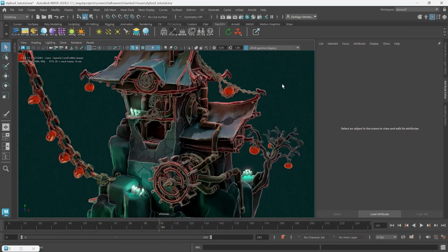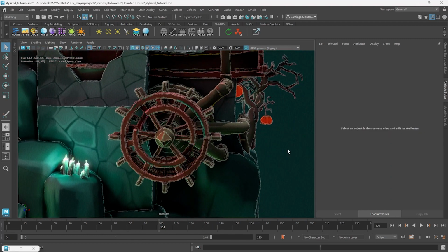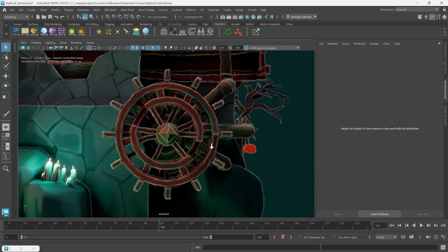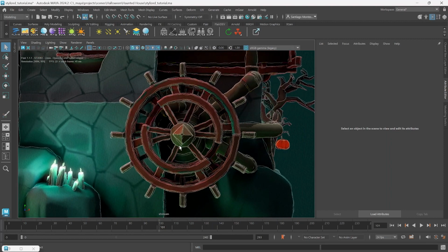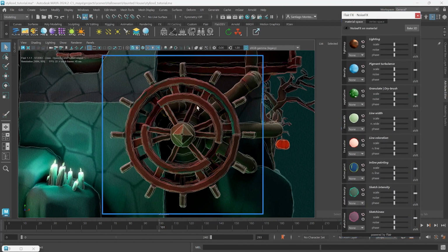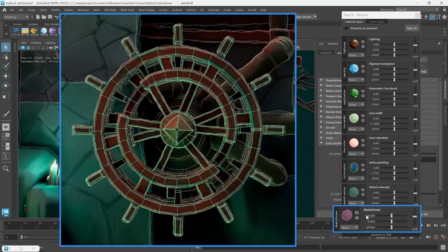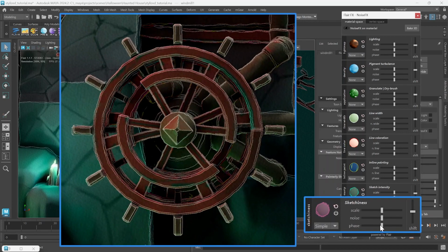Back to art directing. The sketchiness can be art directed with NoiseFX, VertexFX, and Proxies. For example, we can add fluctuations between rougher and cleaner sketch lines using NoiseFX. To do this, we open the NoiseFX tool from the Flair shelf, select the objects you want to affect, and increase the noise effects. You will automatically see how some parts get sketchier lines, whereas on others, the sketch lines have settled and are starting to look like normal toon lines.